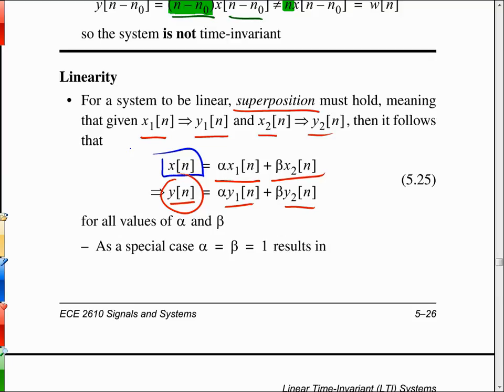It starts distorting. So linearity, the assumption would be if I have just the microphone and the person talking, it's clear. If I have just the music, it's clear. But if I bring the two of them together, now the net signal that's driving the audio amplifier, x of n there, is going to be what? Bigger, right? Because I've got two signals coming together.